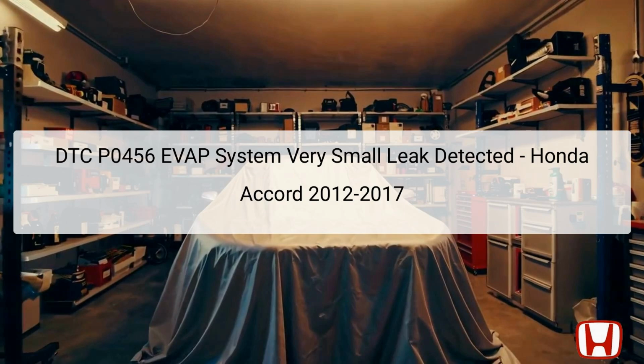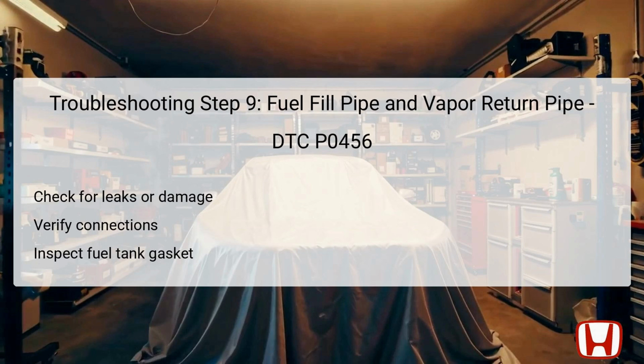this condition. The final visual step involves inspecting the fuel fill pipe and vapor return pipe for leaks, cracks, or disconnections. Damaged or loose connections can compromise the seal, causing small leaks. Also, inspect the fuel tank unit gasket and the tank itself, as deterioration here can lead to vapor leaks. Tightening or replacing damaged parts restores system integrity.